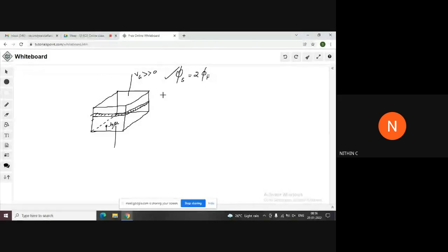And now we should understand a term called threshold voltage. Very important. Last time this was also asked, and the derivation for threshold voltage was also asked. So threshold voltage is actually a voltage. The only voltage term that we know is Vg, right? The gate voltage at which strong inversion starts is called the threshold voltage.